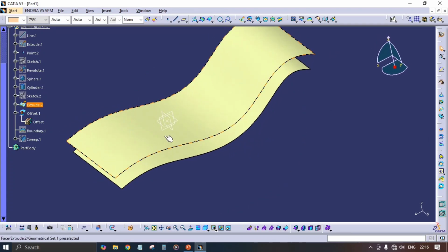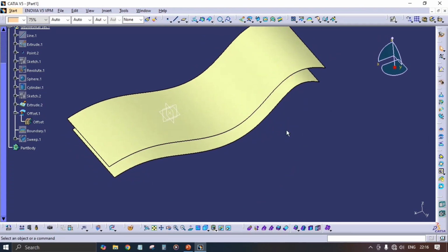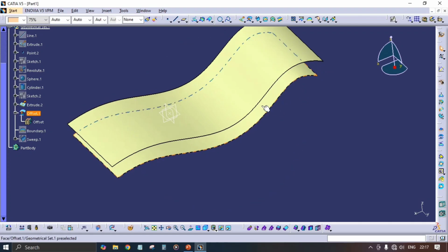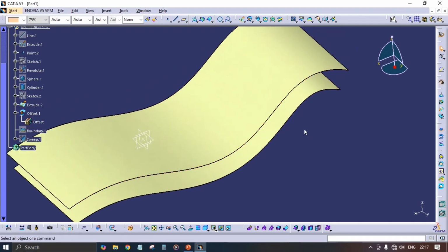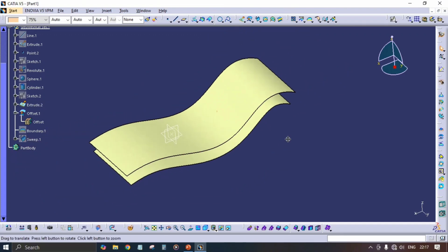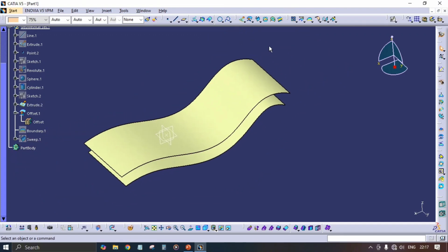With the sweep tool I can extrude, and I have control of the originating side, but I don't have control of the end side. In order to achieve that, multi-section is the best option.